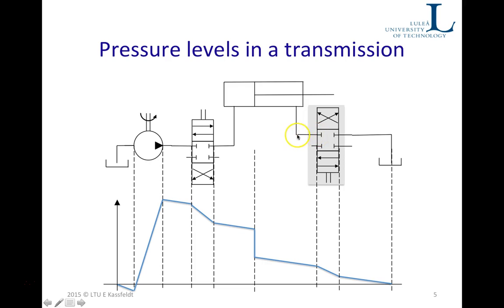I must push it through this pipe. And here we have the pressure difference that corresponds to the outer load. We have to push the fluid through this pump. We need even more pressure to push the fluid over this valve, and this is the point with the highest pressure. This is the level we have to reach in order to have this system going.